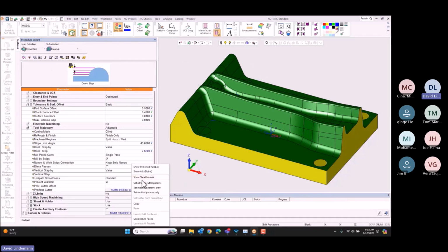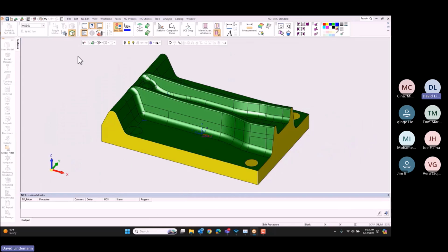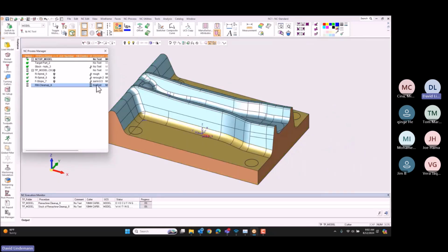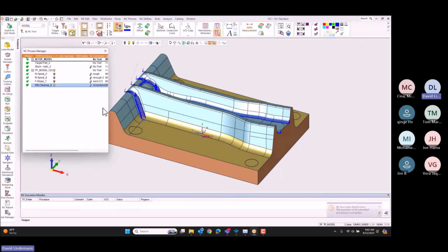A couple of options that are available. Here I'm doing everything from the cutter params, which means load up the speeds and feeds. And again, I don't have to actually go and type those in every time. It's just with the cutter. All right, but the option that's available is if the cutter is too short, and we want to try to get as short a cutter as we can for stability. But if it's too short, then swap it out and finish that toolpath with the next longest cutter. So you can set up a series of lengths of cutters to do that. Or you can say, okay, if it's going to get too short, I want you to automatically tip. So if you have 5-axis, you can incorporate tipping as it gets deeper and deeper, okay?